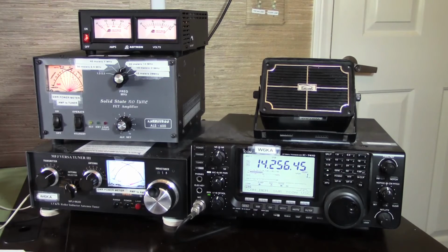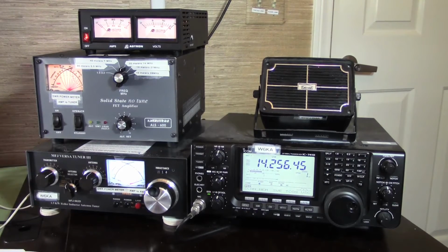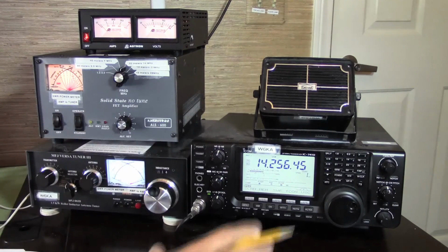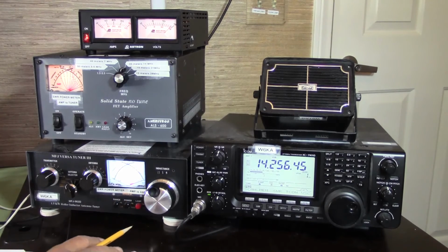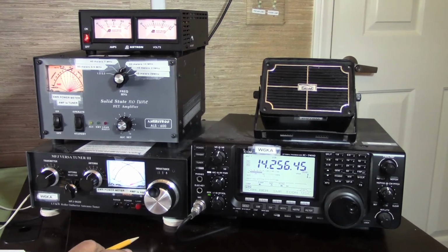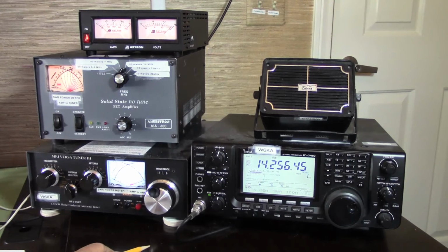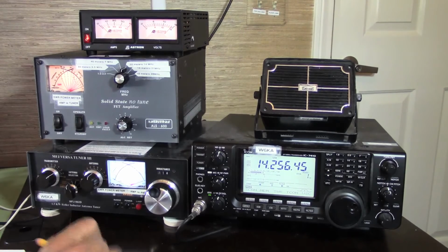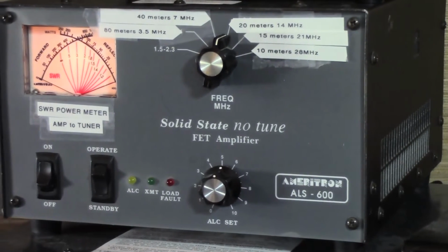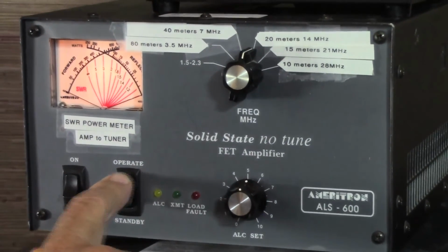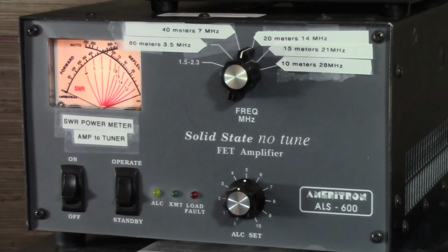One of the things we need to cover is changing bands. Every time you change bands, you follow the same procedure that we just did to find the right frequency and make sure it's tuned adequately. But here are some things to remember, and things that are sometimes forgotten in the process. First, be sure to put the amplifier on standby as the first step, and then back to operate after you finish tuning up.